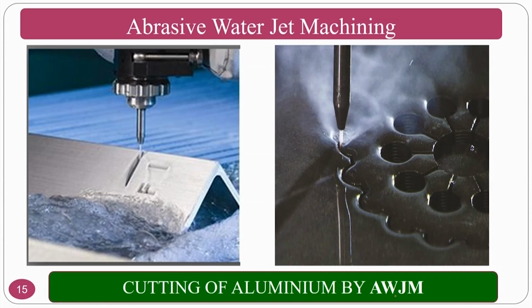Now, you can clearly see the aluminum material cut by the abrasive water jets, and you can see how precisely it is cutting in this region. At the same time, a straight cut is taking place here, because it is a parting action. If you want to cut complicated profiles, complicated profiles can also be cut, and these can be programmed by the CNC control.